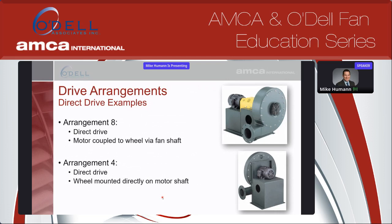The nice thing about these direct drive examples is, now with the common use of VFDs, they're a lot more flexible. You can run these fans over speed, over the motor synchronous speed, or below the synchronous speed, as long as you take into consideration motor safe speeds and fan safe speeds in the design. So they're a lot more flexible than they used to be, because before you had to select these at a motor synchronous speed, and you were kind of stuck there. But now with VFDs, there's a lot more flexibility.